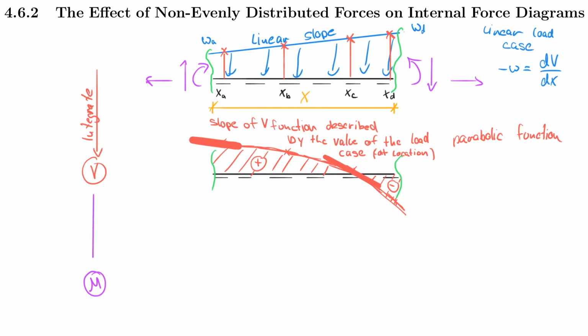So let's highlight that one more time. So we integrate. And if we integrate, we know that at this location we must have a local maximum or minimum. So when we integrate the shear force function, then we go through 0 right here, and therefore we must have a maximum in our moment diagram. So let's go ahead and draw the free body diagram, or a cutout of that. And let's include that we now have to consider a local maximum or minimum.